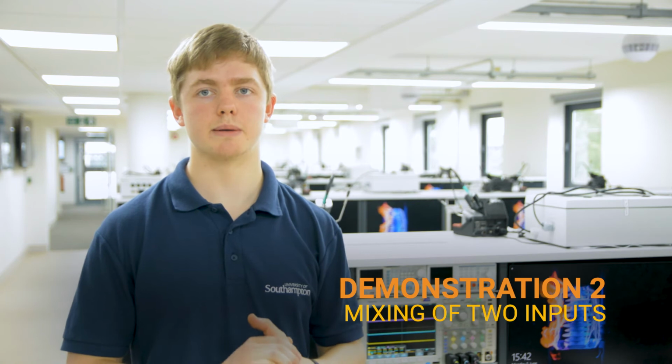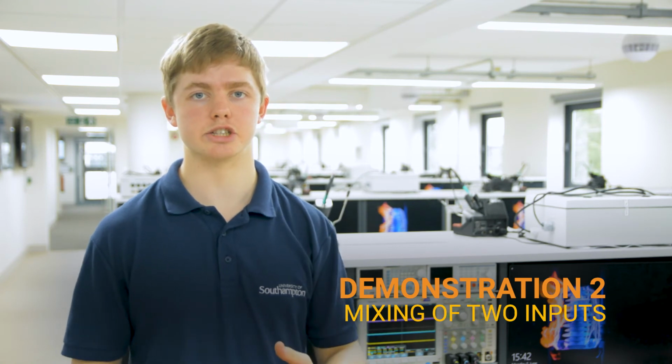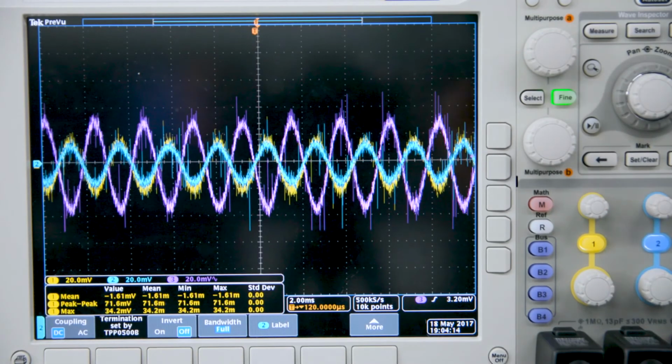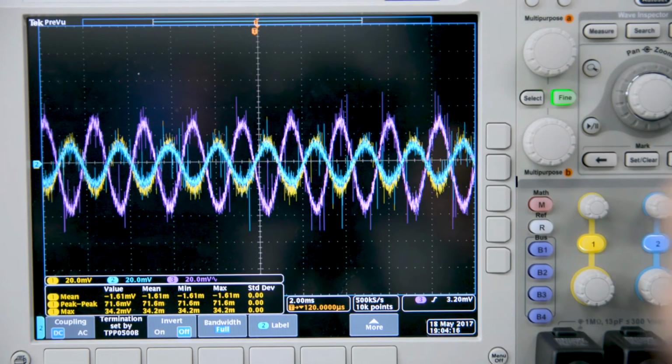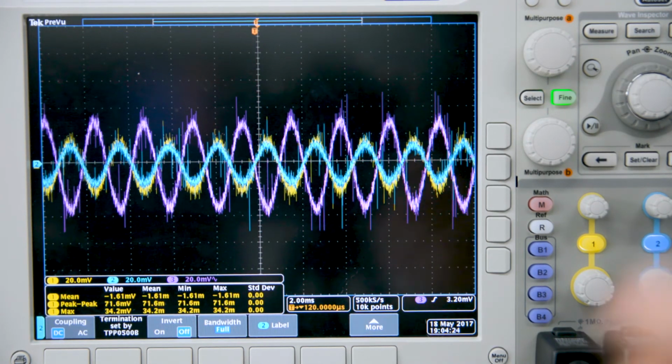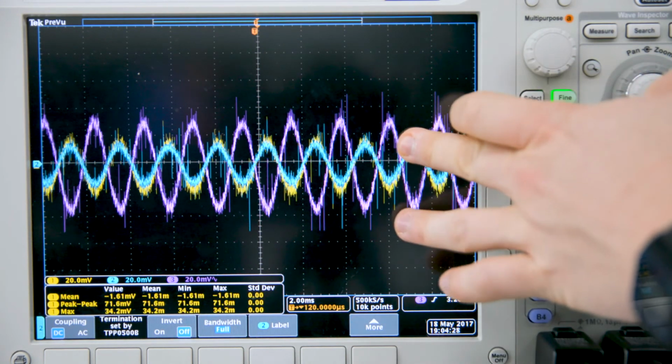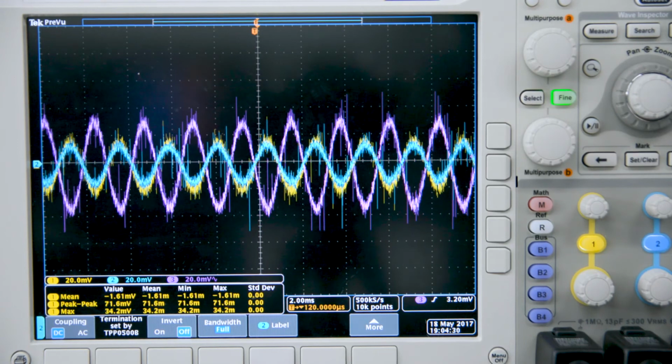Now we'll see how the op-amp circuit can actually be used to mix the two input signals coming in from the phone. So now we really start to see the benefit of using an op-amp to mix the signals instead of just a resistor network, because we can maintain the gain throughout the system. With just a resistor network there'd be losses, but with an op-amp we can keep that at that one gain, that unity gain, and while it's not implemented here, we could even add gains. So say a small input from a microphone could then be amplified up to something useful.